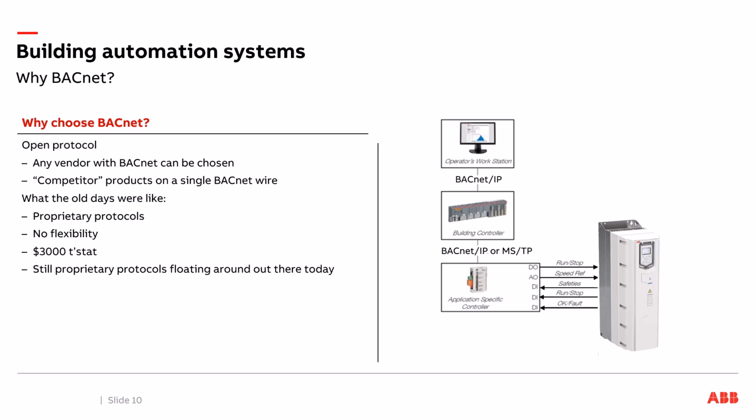So why choose BACnet in the first place? Well, I just talked about it's an open protocol. It's that English-speaking language, the one that we're all talking today, so any vendor can be used. It allows all those competitive devices to be able to share a single wire and talk to each other.